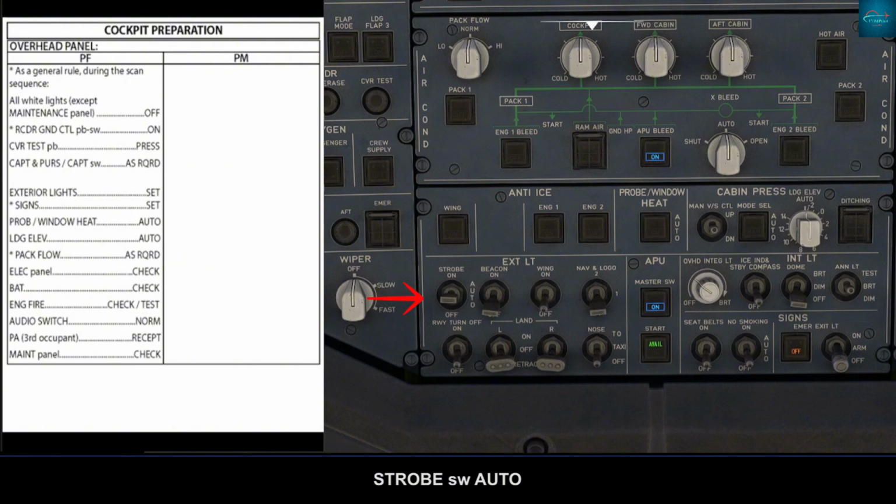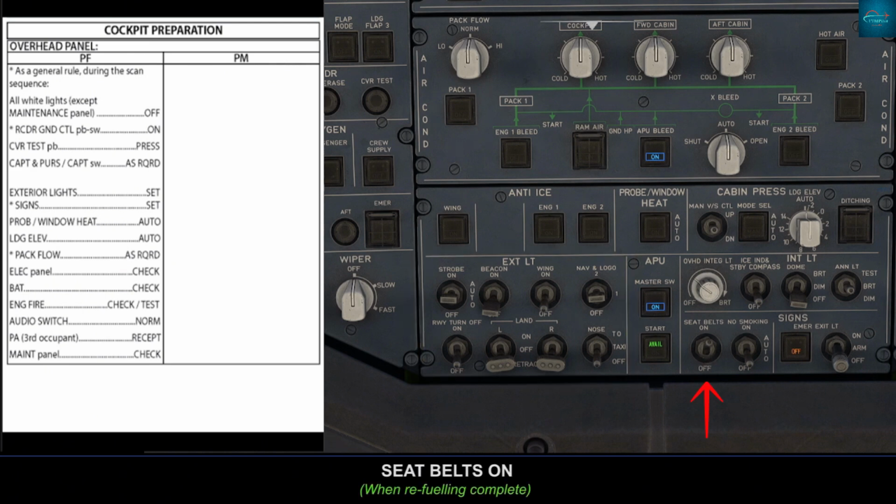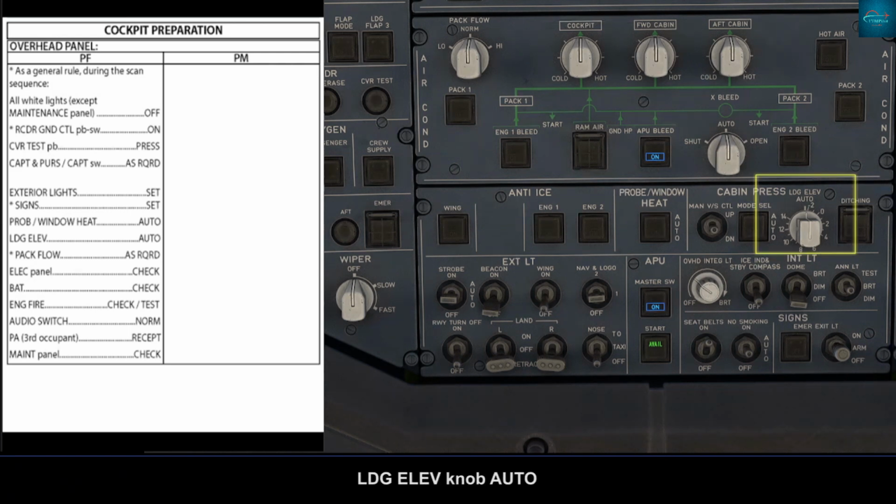Strobe switch auto. Nav and logo on. Remaining exterior lights off. Seatbelts on. No smoking PED to auto. Emergency exit light selector on. Landing elevation knob auto.